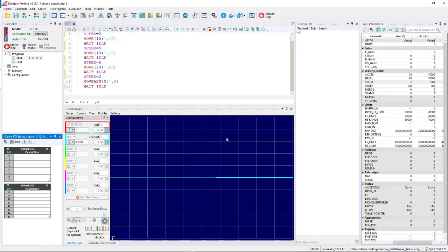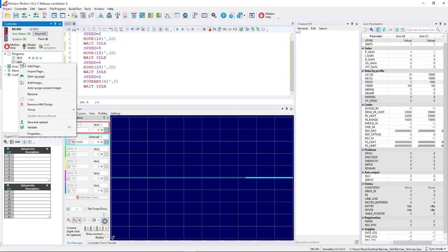It's just a matter of the size, width, and height of the HMI. That's it. So once you create and choose the HMI, it will pop up a new option which shows the HMI option. If you right click over here, you can add a page.